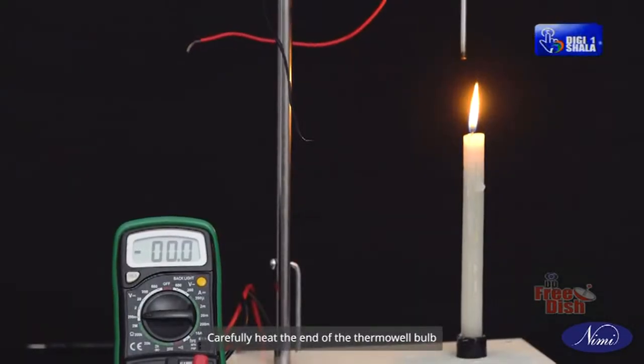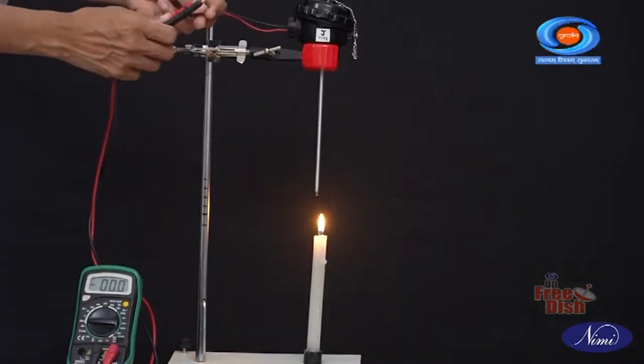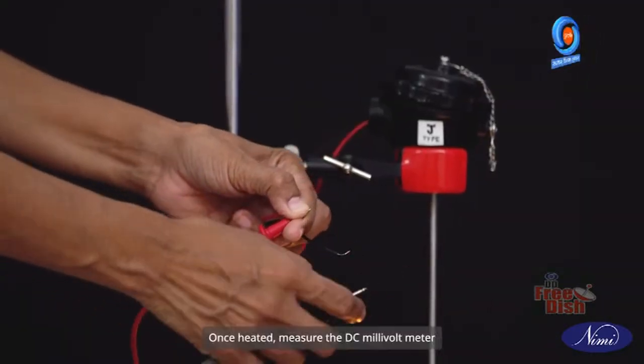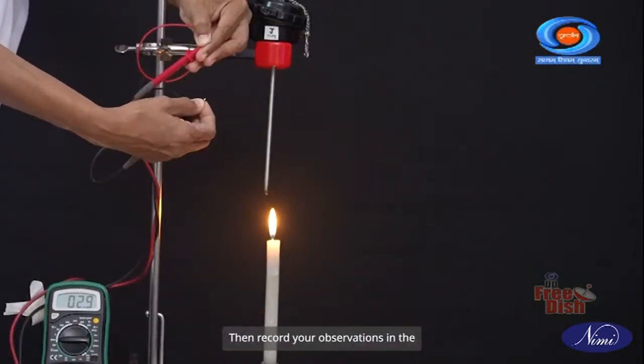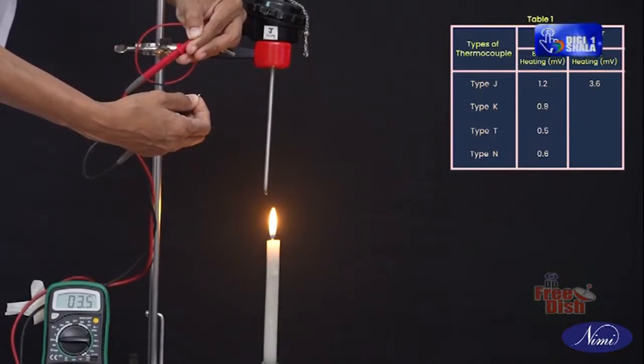Carefully heat the end of the thermowell bulb by exposing it to the flame from the candle. Heat it uniformly until it reaches a stable temperature. Once heated, measure the DC millivolt meter reading on the digital multimeter. Then, record your observations in the designated table labeled Table 1.